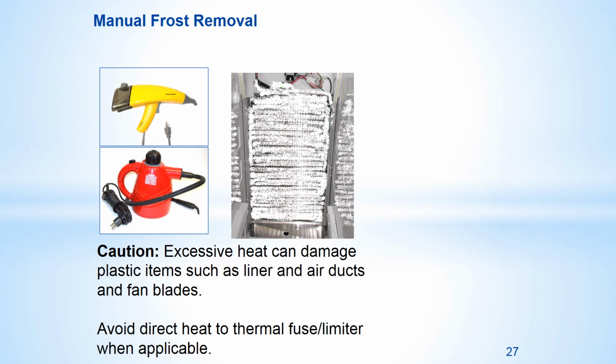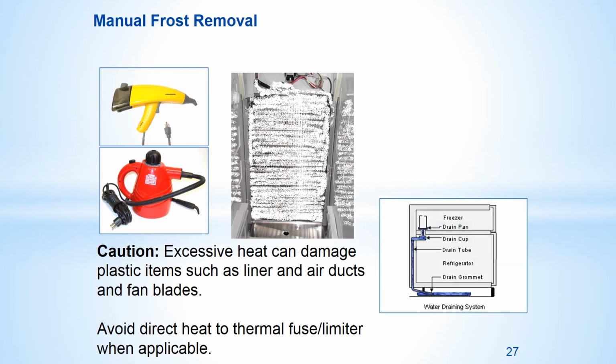A steamer is the preferred tool over a heat gun and can also be used to clear drains and remove ice from evaporator covers before disassembly. You still must use caution though, as some styrofoam air ducts can be permanently damaged.